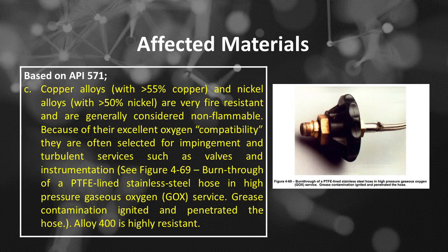Number C, copper alloys, with greater than 55% copper, and nickel alloys, with greater than 50% nickel, are very fire-resistant and are generally considered non-flammable. Because of their excellent oxygen compatibility, they are often selected for impingement and turbulent services such as valves and instrumentation. See Figure 4-69, burn-through of a PTFE-lined stainless steel hose in high-pressure gaseous oxygen, or GOX, service. Grease contamination ignited and penetrated the hose. Alloy 400 is highly resistant.